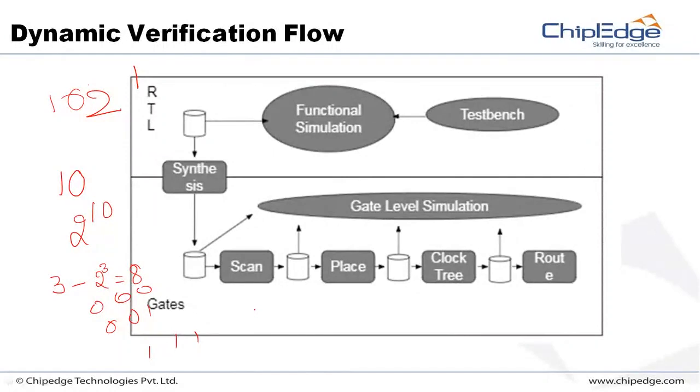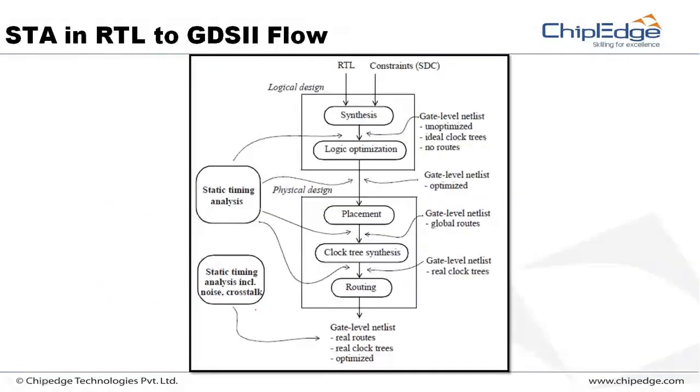So it was very time consuming. Now with gate counts of 10 million, 100 million, they say, in an IC, with that huge count, this was not good at all with respect to time. It used to take hours and days to do it. So hence they switched to STA. Now there is no dynamic timing analysis. People won't do it. It is only STA they do in the industry.